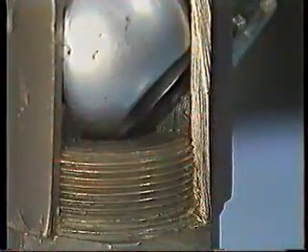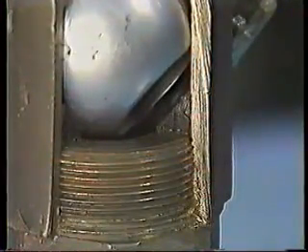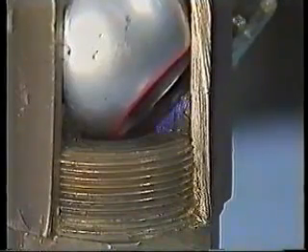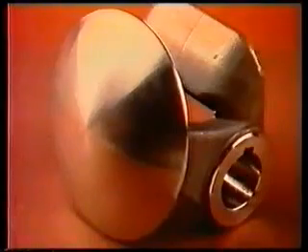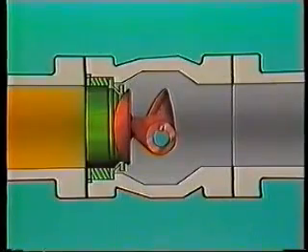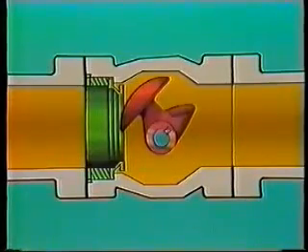In the throttling position, high fluid velocity will rapidly erode the partially exposed seat ring and the edge of the port opening. A ball valve, however, can be adapted with a special plug that makes throttling service possible. The plug is positioned off-center in relation to the seat ring so that it won't make contact with the seating surface until shutoff is complete. This allows equal flow around the full area of the plug even when the valve is only slightly open. Because flow and pressure are distributed equally across the plug, the valve can be throttled without excessive erosion.